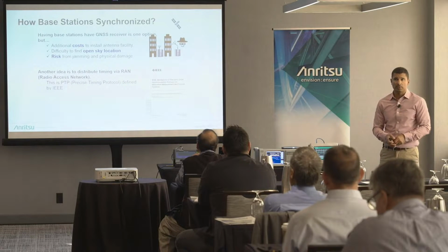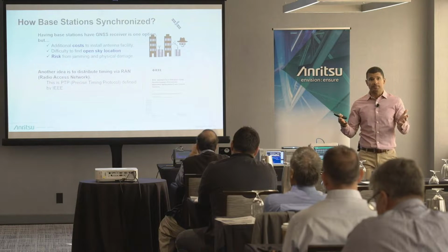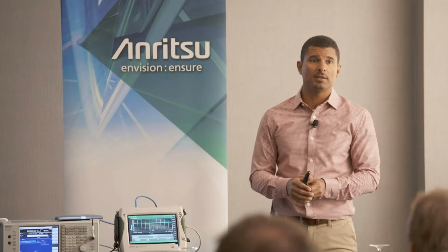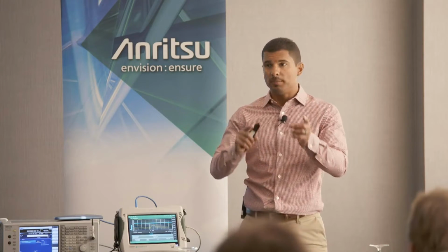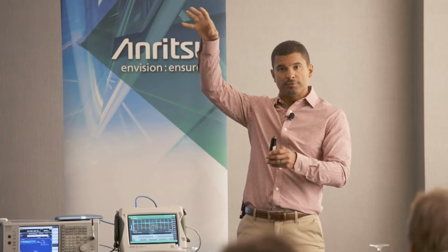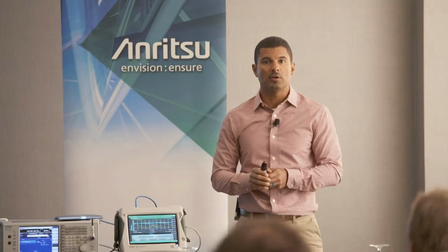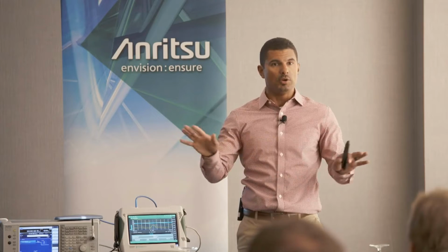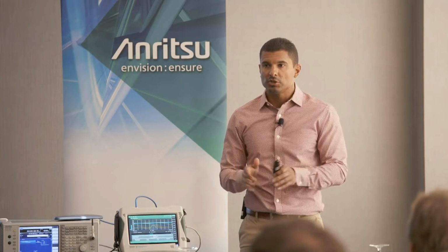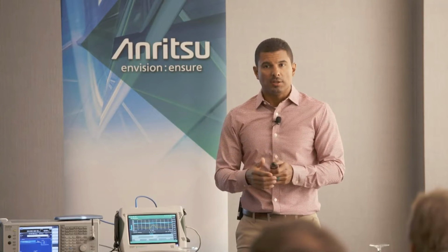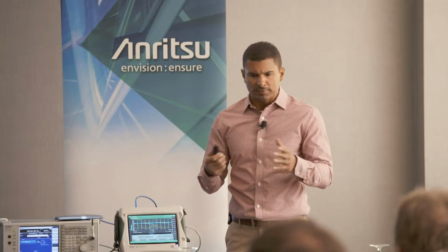So how are base stations synchronized today? GPS, right? Most of us have GPS on those antennas or at the sites, the big macro sites, or you're on top of a roof, rooftop installations and so on. Clear line of sight, no issues with GPS. Here's the challenge. In 5G, and let me know if this is new or if you've heard this before, the whole idea is to get those radios to the street level, right? You're starting to see 5G on lampposts. You're starting to see 5G on traffic lights.